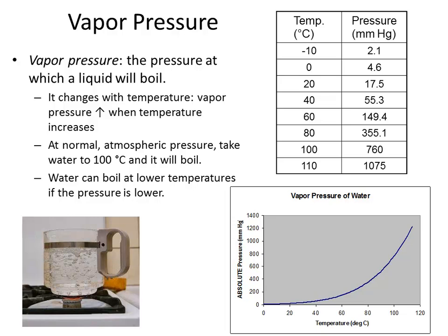We've spoken before about vapor pressure and how when water boils, that's an indication of either the fact that the temperature has been elevated up to the vapor pressure, up to atmospheric, where the vapor pressure and the atmospheric pressure are equal by either elevating the temperature of the water to increase the vapor pressure, or you can decrease the pressure of what surrounds the liquid until it starts to boil. And so these little bubbles here that are inside of boiling water, they're not air bubbles, they are H2O bubbles. That's water vapor that is inside of there.